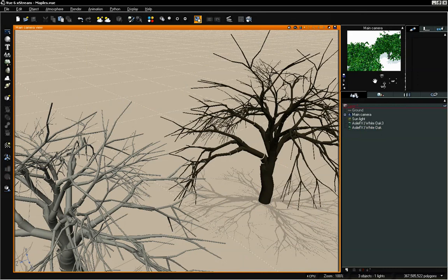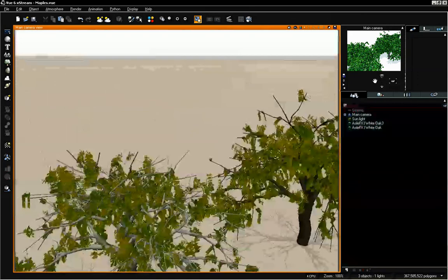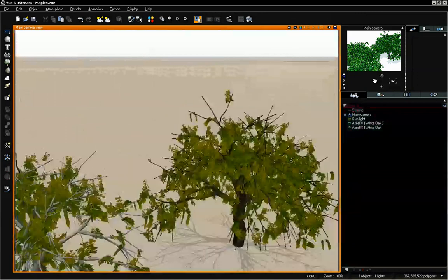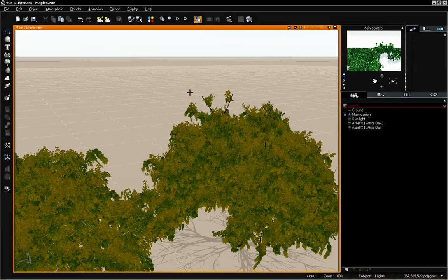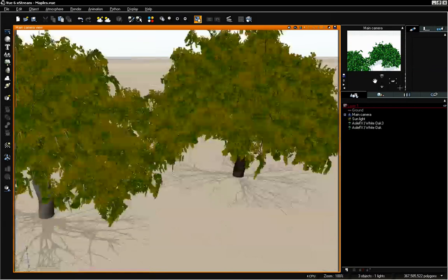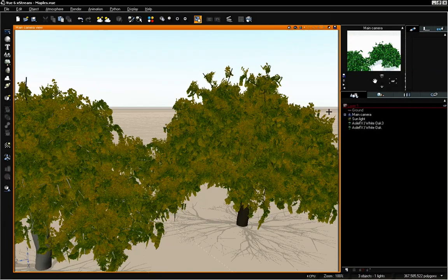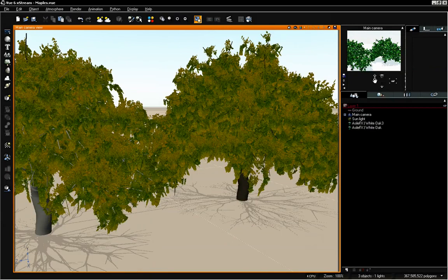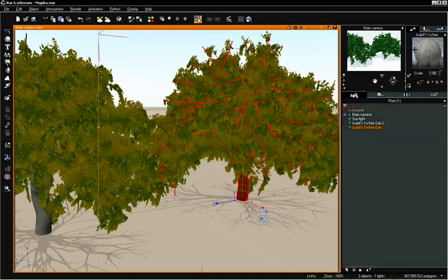You could also save out your material, which is an ecosystem-based material, and populate this on other trees or on other objects and use it over and over again. So once you have that initial ecosystem created in that bark surface, you can go ahead and copy that over to any plant if you want different branch setups, smaller amounts of branches, and a lot of different variations between different species. You could just go ahead and copy that material from one, which we could do right now.